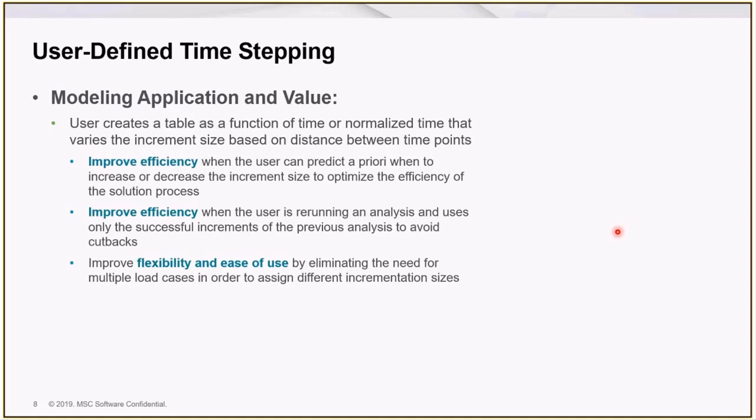The second situation is maybe you didn't know, you ran it initially. You now know how the problem is going to solve based on the incrementations that were successful, and you bring those successful incrementations back into the next run that you might do, avoid cutbacks, and maybe change the incrementation to optimize your runtime.